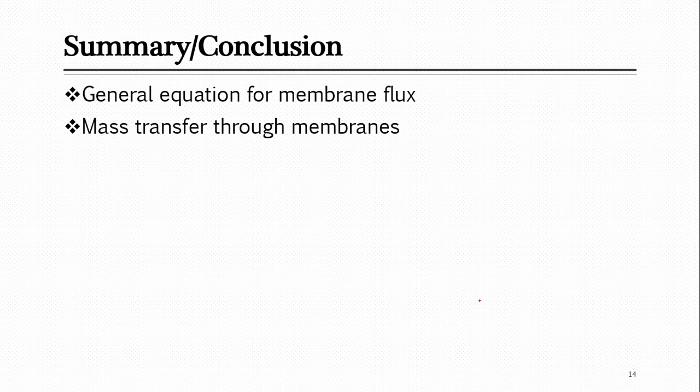Up to here, today we have discussed some basic terminologies, or revised those, like diffusion, osmosis, what osmotic pressure is, and how osmotic pressure is important. We discussed the major equation, the general equation which accommodates a lot of parameters for membrane separation, that's the flux equation, and how flux is affected by the applied pressure across the membrane, or transmembrane pressure, as well as osmotic pressure due to the membrane material, and also the formation of gel or cake on the surface of the membrane.